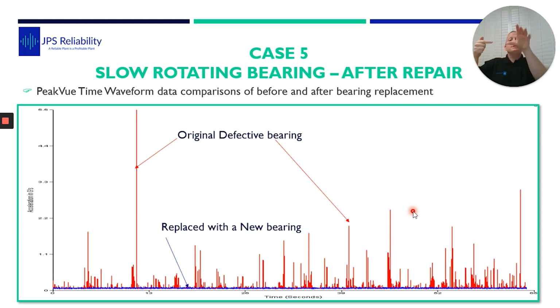And one point of the bearing had the higher damage on the inner and outer race, and that's opposite the greasing point. So it was as if the grease, when it is greased, would come out and couldn't totally replenish around the opposite side. And after 5 years of all the stress of the dynamics of it moving and the weight, it just spoiled and failed. And perhaps if they had more grease points around it, they may double their life and actually reach 10 years.